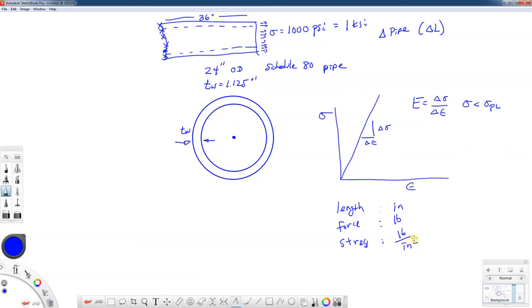So when I put in my number for my stress, if I put in 1, and I'm thinking, well, I got 1 KSI on it, well, really what that would be applying to it would be only 1 pound per square inch. If we want 1,000 pounds per square inch, we need to put in 1,000 into our load dialog box that we'll see in a minute.